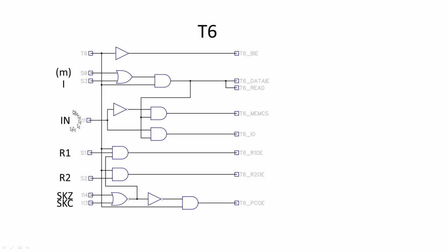And in is for the I/O, so that's not an I/O, must be memory, so memory chip select comes on. If the in instruction, which is instruction 11, is on, then this one won't come on, and we'll get an I/O signal to say it's an I/O signal we want, an input, rather than memory. So that's that simple bit of logic. And of course we can do this for immediate mode as well.